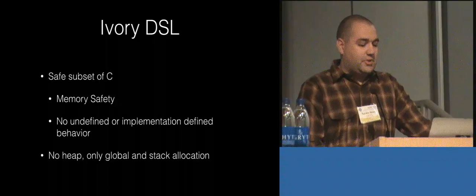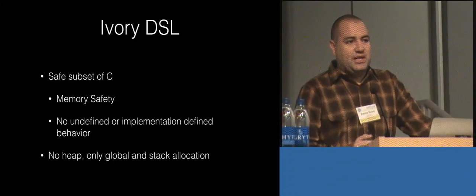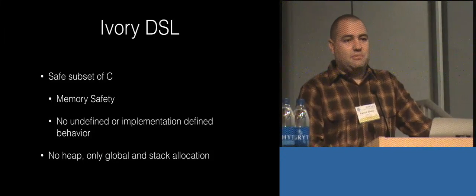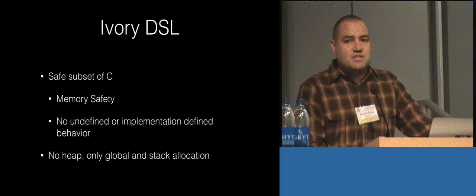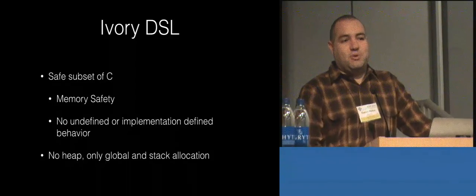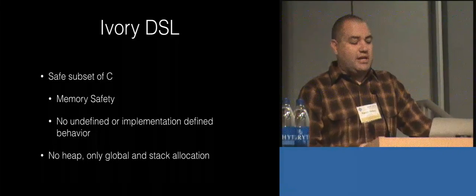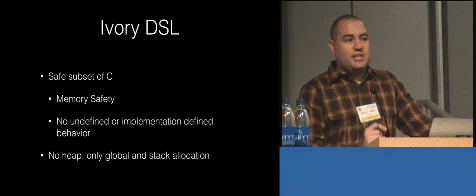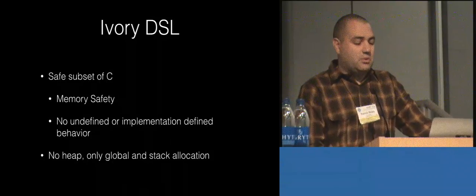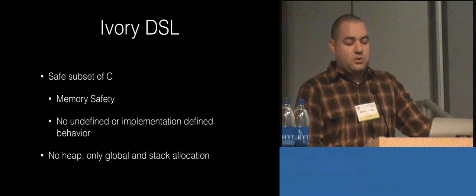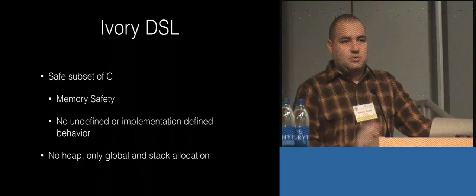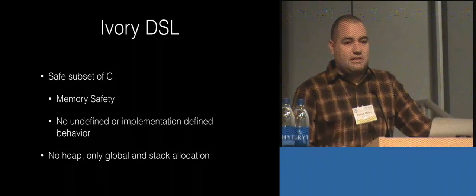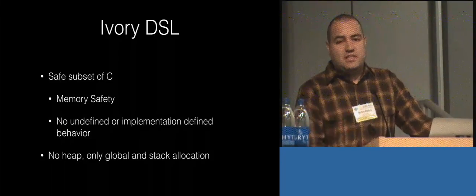So there's a lot of integer behaviors and pointer behaviors that we wanted to completely eliminate from being exposed to the user. And the other thing was, in this embedded system space, you want the programs to be deterministic, you don't have very much RAM, there's very often no heap in these systems. So we decided that there would be no heap in the Ivory language. You would only be able to allocate global variables, like global C variables, and variables on the stack, which is the simplest heap.